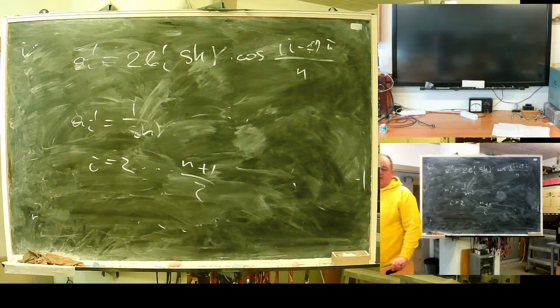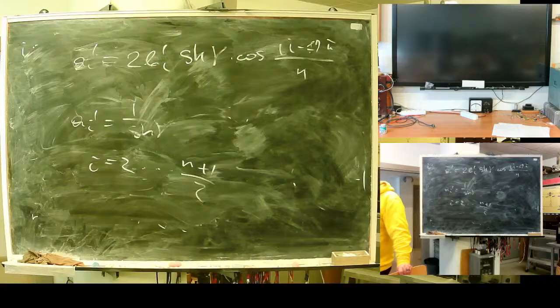There also are Bessel polynomials. I will bring a large universal table with filter factors. But in general, today you can easily find filter design software. Filter factors are not the problem. What is the problem? First, you need to strictly define where the working frequency of your device will be.